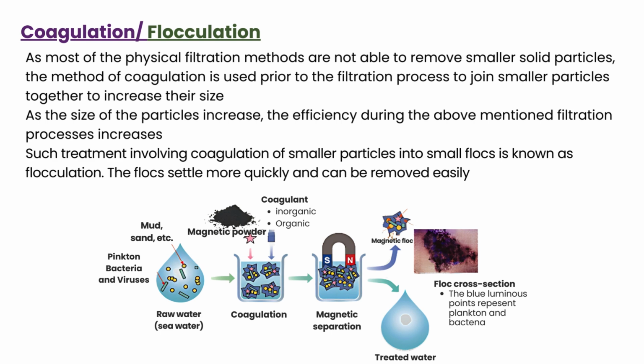At this stage, water treatment polymers may be added to strengthen the floc and increase its settling weight, making it easier to remove. Eventually, the floc will achieve optimum strength and size and is ready to be separated from water. The stage that follows is usually sedimentation.